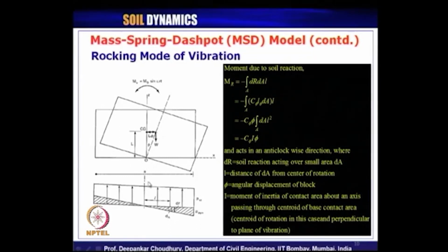In that case, what is the pressure distribution going to be developed below the footing? There is a static uniform pressure and then this variable dynamic pressure at the base of the footing. Because of that, what moments are getting generated? Because of this dynamic, unbalanced pressure, some moment will be generated. So, the moment due to soil reaction is nothing but that component. Then from the displaced position of the Cg, some moment will get generated, and this is the externally applied moment. So, the sum of these three moments will